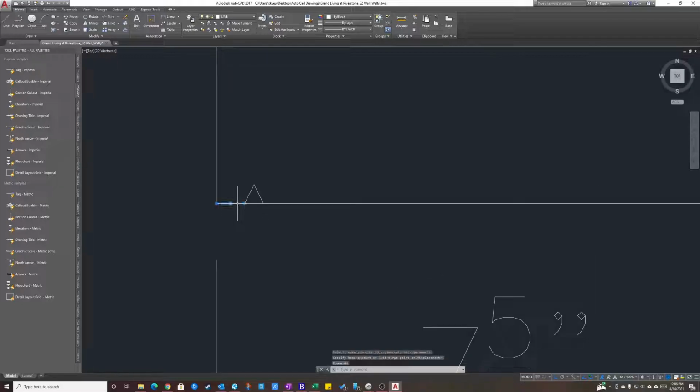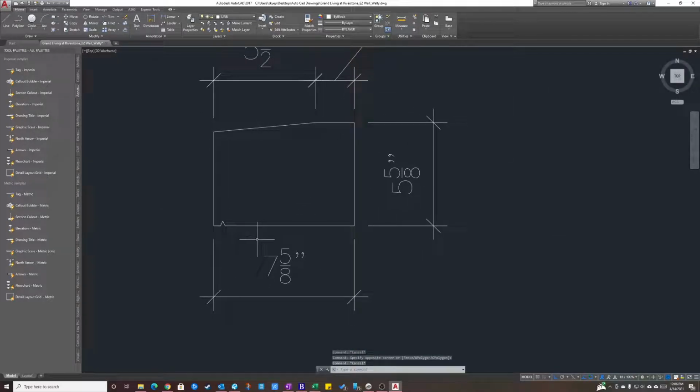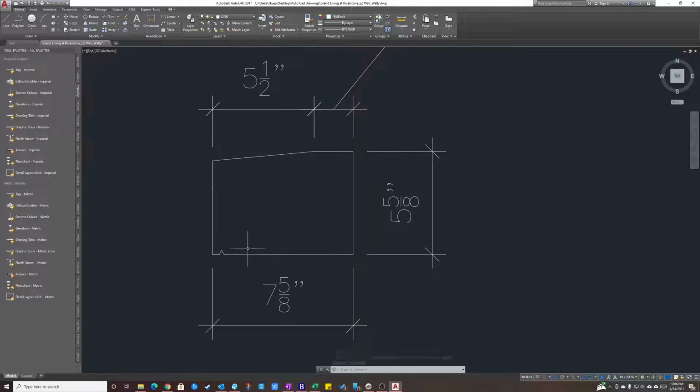Now you want to select the line that you drew, which was the 3/8 line, just to verify that it's there. So it's good. Don't erase it. Hit the escape button. Now select your trim tool, right click to activate it, and click on that line that's separating the triangle from the rest. Now you have a non-segregated line that separates your triangle, and that's an accurate representation of what a drip edge is.